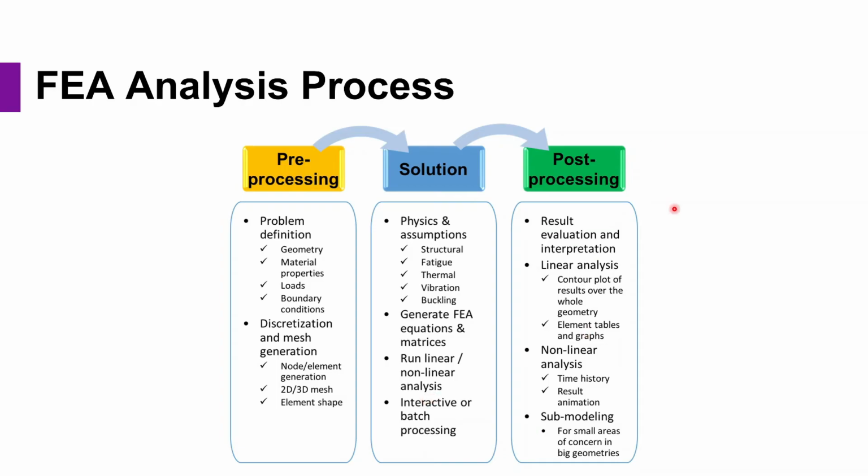Once you solve the model, we reach the post-processing, which is the main aim of FEA. You will now get the results. Within the results, you will be able to visualize them. For instance, you can get a plot out of it. You can make an animation to see how it's going to perform in reality. And now you need to interpret the results you get and write a report based on that. For instance, where is the failure area? What's the maximum amount of stress that I have? What's the area where I will get the highest stress? And so on.